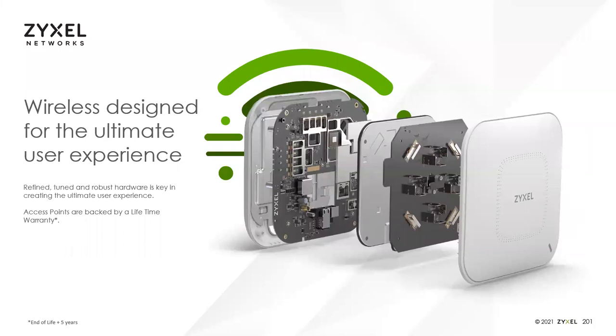There's no moving parts. So one of the leading causes of failure over time is something called heat fatigue. Heat builds up. It can cause solder joints to fail. It can cause the little teeny tiny switches inside the chips to fail and be locked open or closed, etc. So all of our APs are going to have this metal sheet behind the PCBA. It's essentially a heat sink that's designed to pull heat off the components on the board and vent them out the back of our access points.